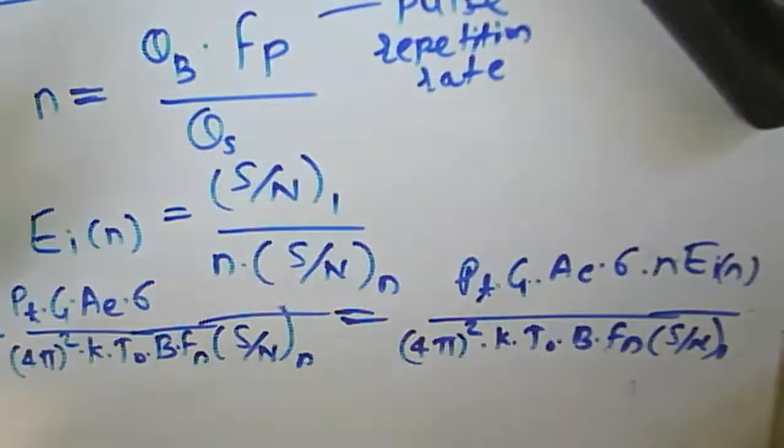Okay, so likewise we are modifying the radar equation with respect to the integration of pulses factor, and here we have expressed the bandwidth and noise figure. Okay, so this way we have improved the radar equation. We will talk about the radar cross section of a target, then the transmitter pulse, how much transmitted power there, and everything in the next lecture. So with this, we stop here. Thank you all of you.